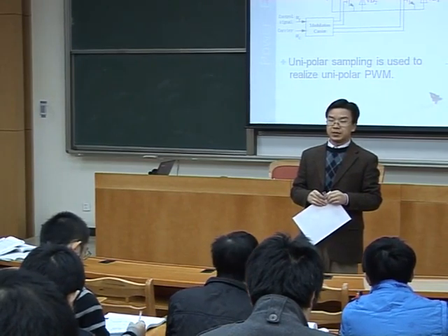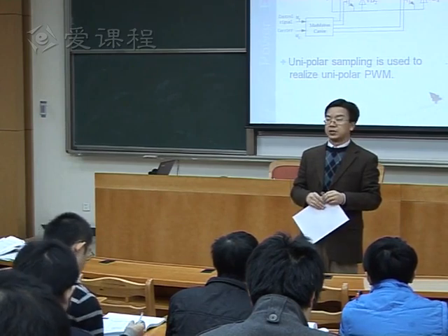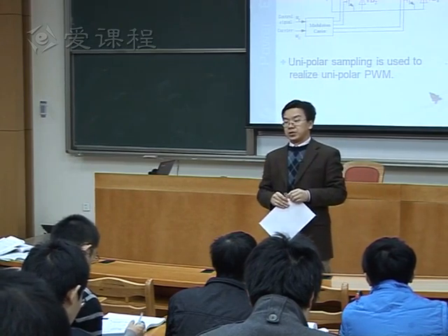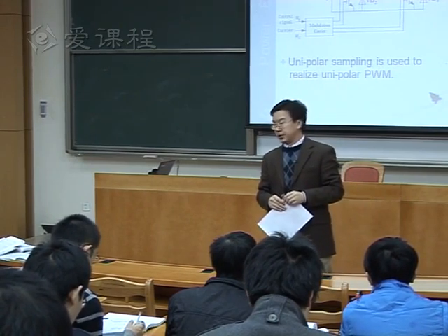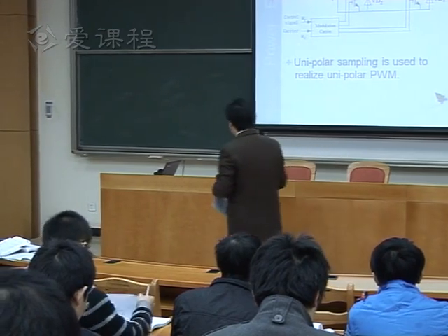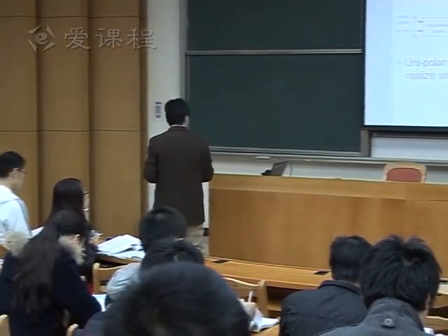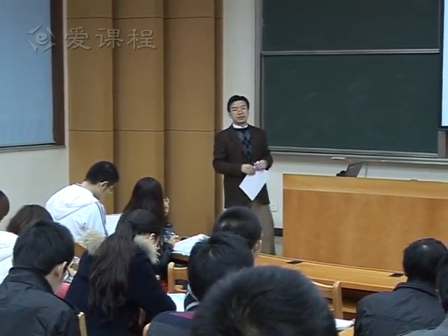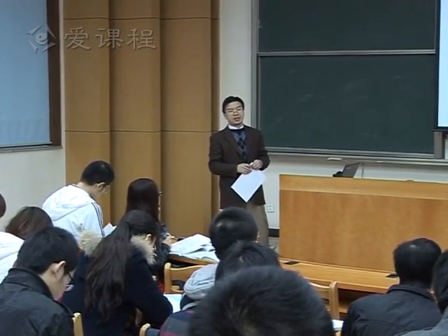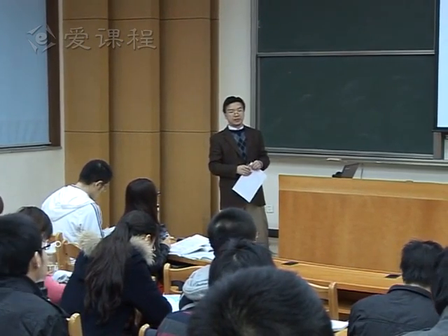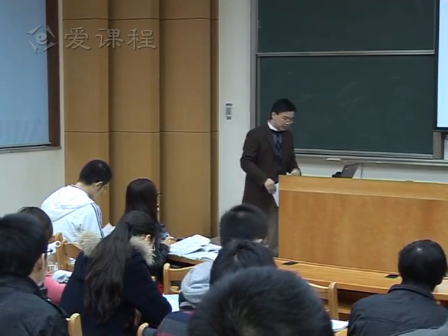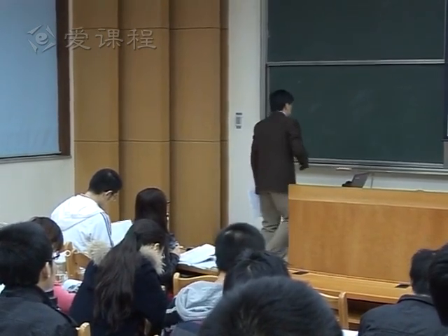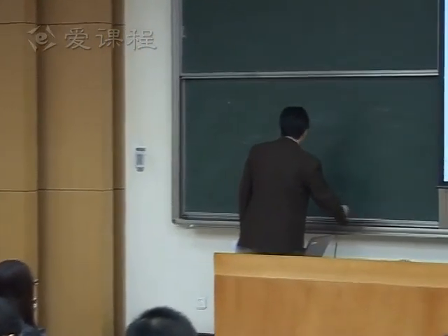So with PWM technique, we can theoretically emulate any kind of waveform we want to emulate. And then we start to talk about the different techniques to implement this PWM idea, pulse width modulation idea. And the first one we started to talk about was sampling, triangular wave sampling method.